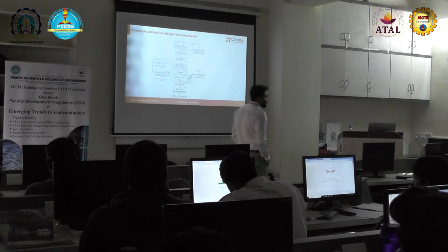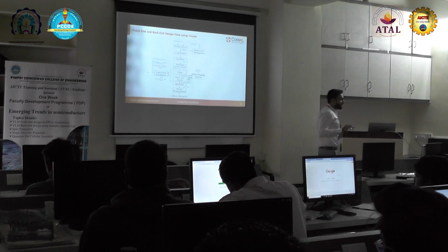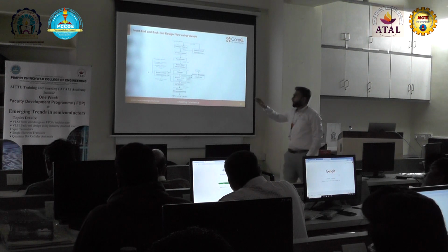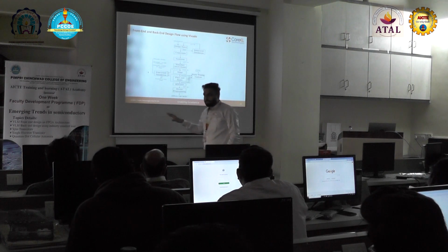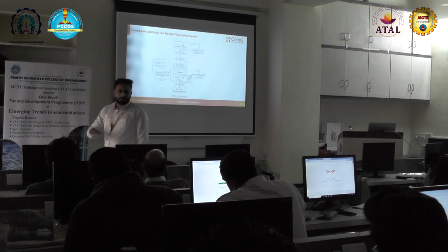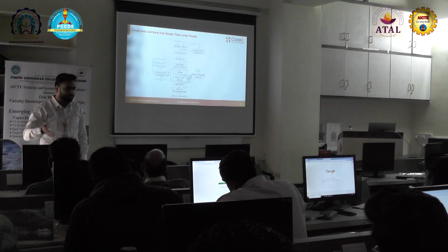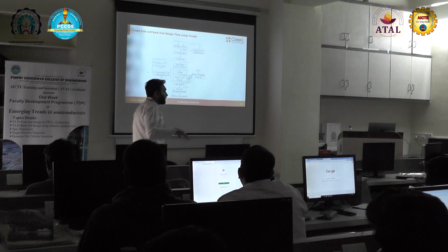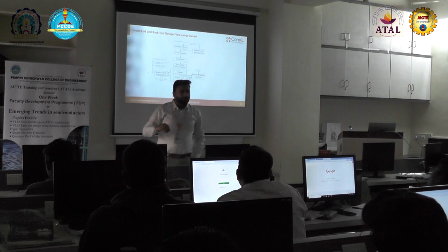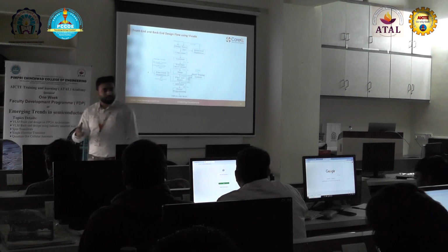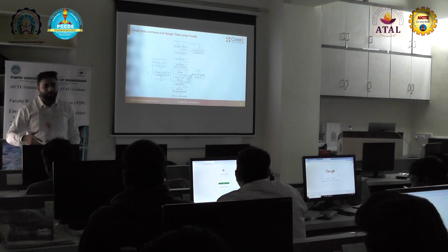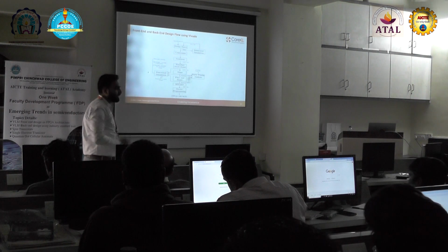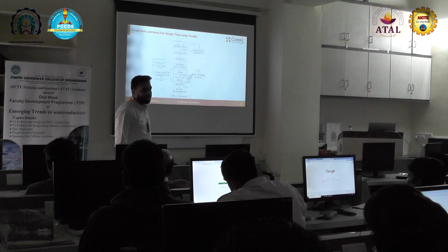In the implementation stage, optimization, placement and routing will be done. Once the placement and routing has been done, I will get the reports. We get reports in the synthesis stage also, after synthesis, and we get reports after implementation also. But what is the difference between the generated synthesis report and the implementation report? Any idea?